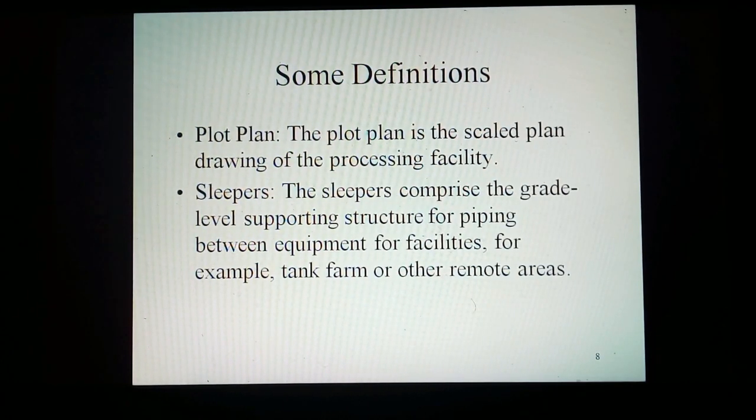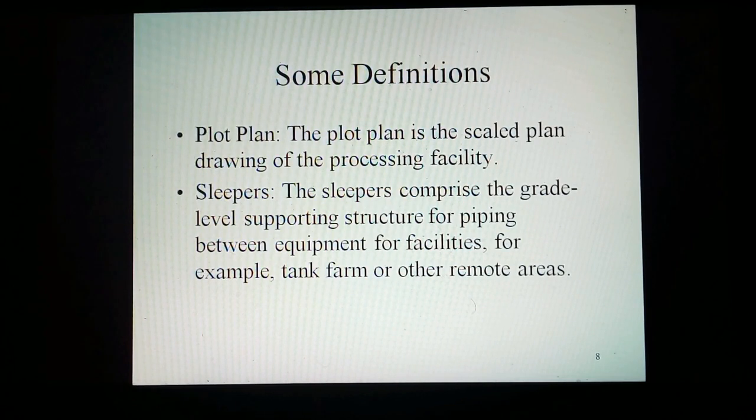Plot plan. The plot plan is the scale plan drawing of the processing facility. Sleepers. The sleepers comprise the grade level supporting structure for piping between equipment or facilities, for example, tank farm or other remote areas.